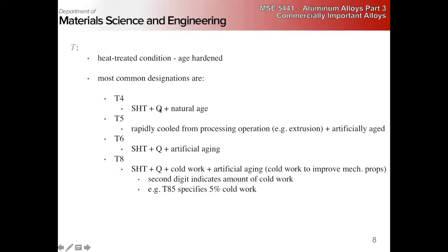Then when you use them, you let them come up to room temperature, and you only have a short amount of time that you can use them because they will naturally age at room temperature to get the full hardness. So if you let them sit at room temperature for more than an hour or so, they'll be too hard to buck to set the rivet in place. So those are what are called icebox rivets. They will naturally age to their full hardness at room temperature.